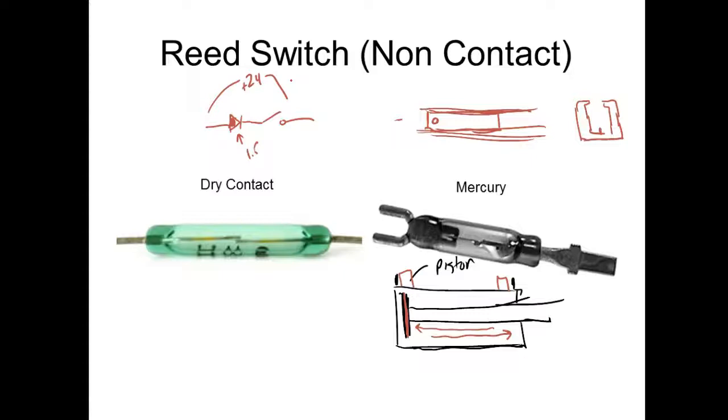And we like indicator lights because if I don't have an indicator light, that means I got to get my dang meter out and put it across the switch and see if it makes and breaks. If that little light comes on, it means that switch is made. If the little light don't come on, it means the switch is not made. Which means what? I either got it out of adjustment or the switch itself is bad, or there's an open in the circuit somewhere.